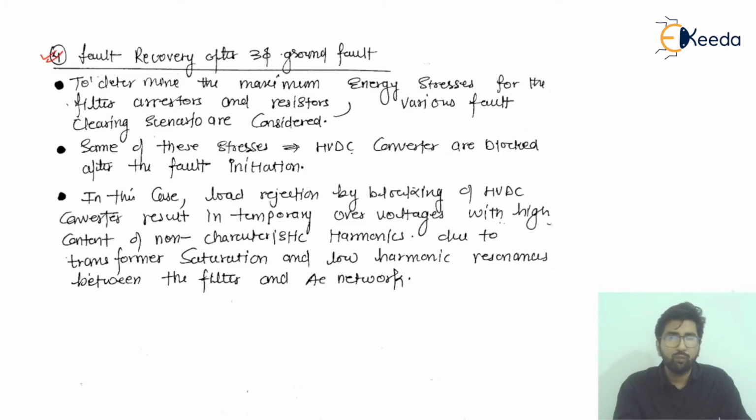Now the fourth point, the fault recovery after the three-phase ground fault. I have considered 3 points in this category. The first point is to determine the maximum energy stresses for the filters, arresters and resistors. Various fault clearing scenarios are considered, and in some of these scenarios the HVDC converters are blocked after the fault initiation.